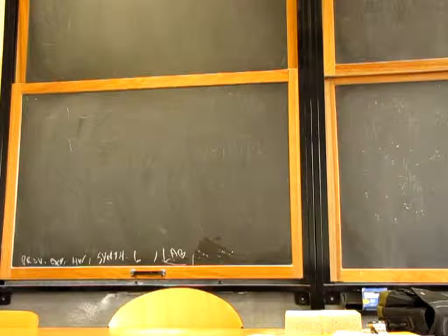It's very hard to mount a power circuit, a switch mode circuit, on a breadboard and have it work. If you had the class with Professor Sansoe, you mounted a buck converter, but it's very critical if you mount with wires. It must be on a PCB with low inductance traces.